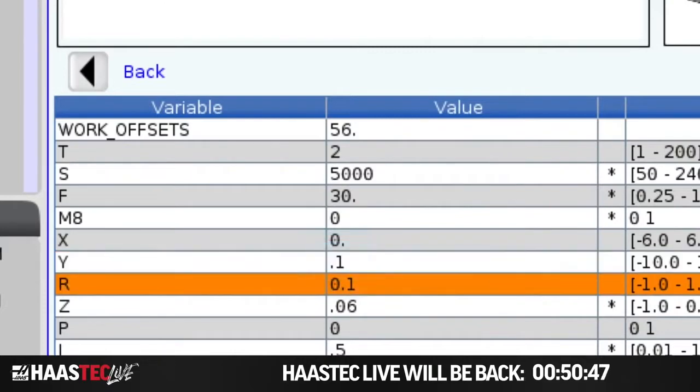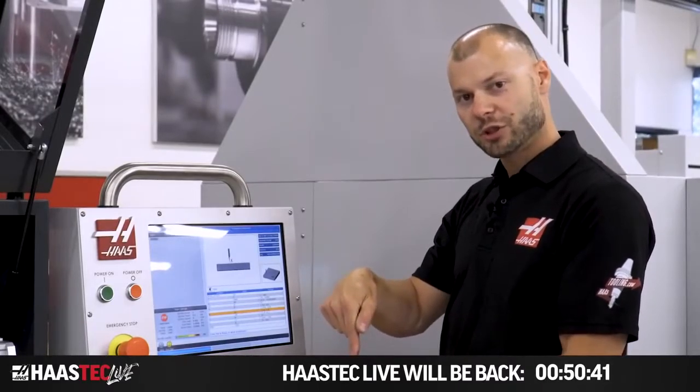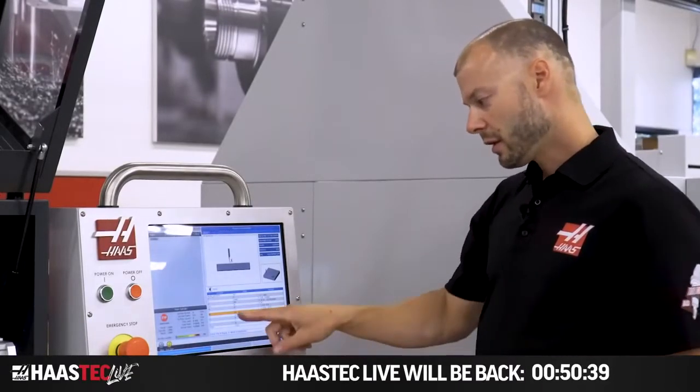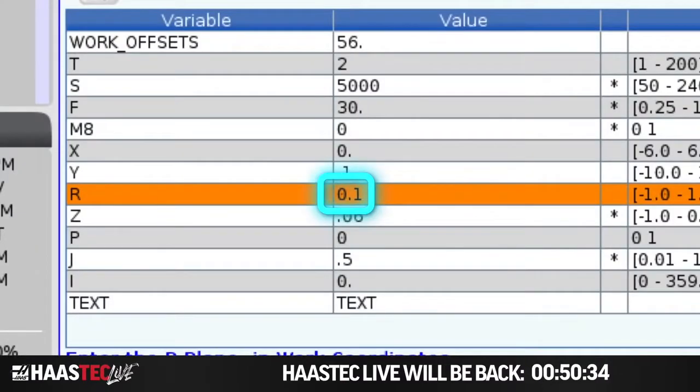Now here is my rapid plane. The rapid plane is where the tool changes from G0 rapid approach to a G1 feed move. The default we have in there is 100 thousandths of an inch. I'm going to leave that alone because that's a pretty industry standard number.